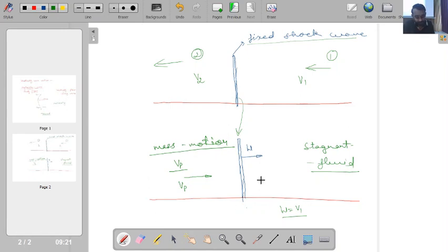And for a certain set of cases, we can analyze this second situation by using the assumption of the first situation only. As I explained, in the case of an aeroplane, I can place the observer on the aeroplane itself. So with reference to him, the shock wave can become stationary and the fluid can be moving. But as I told you, there are certain applications for which we cannot purely go with this type of stationary wave analysis, and we have to consider transient or unsteady wave motions.